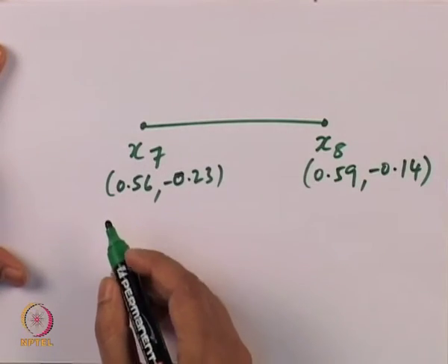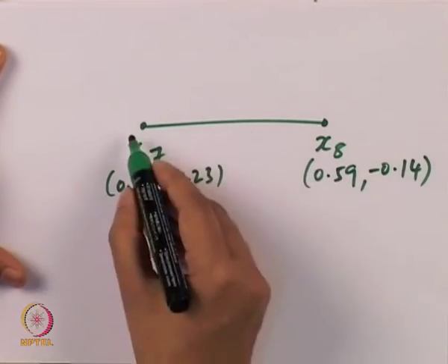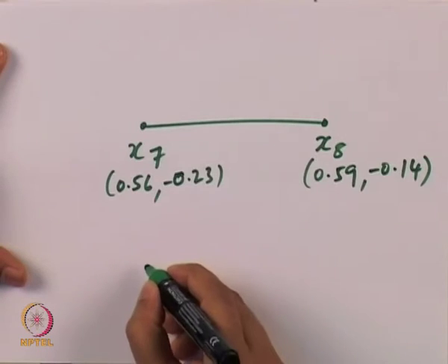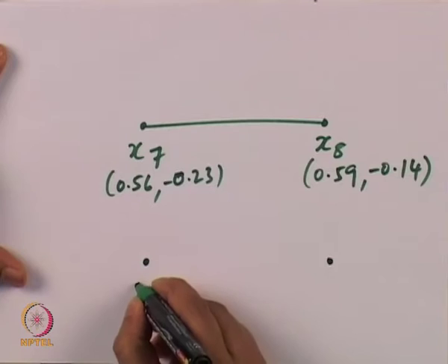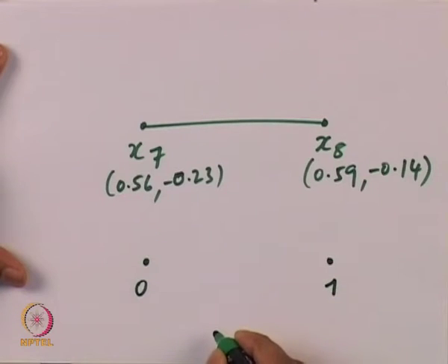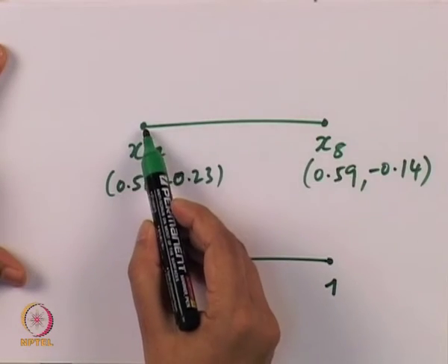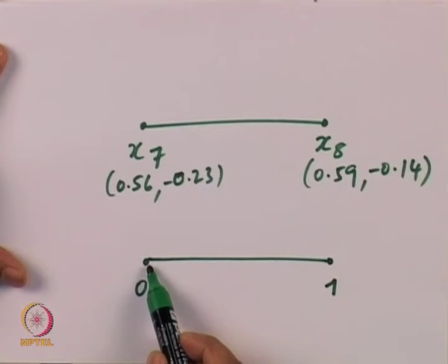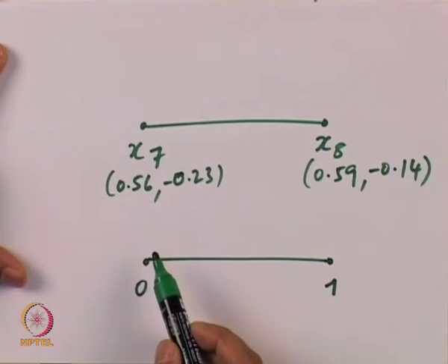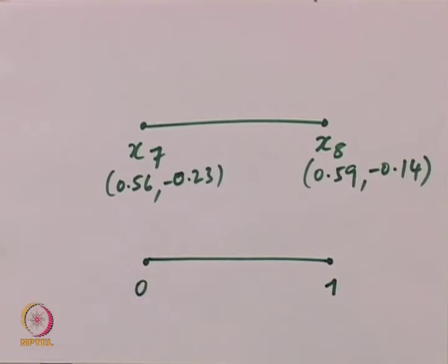So what we do is we forget this and we try to map any physical element to an arbitrary reference element whose points are always going to go from 0 to 1. The reason for doing this is very clear, where each of the points inside the physical element can be uniquely mapped to a reference element, and we know that this mapping is unique because each of the points will be uniquely referred here. So that's what we are going to do.